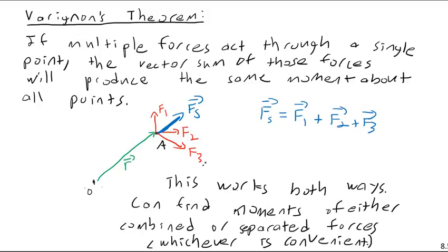Now, where this is really useful is especially for two-dimensional problems. When I say separate forces, that includes components. In many two-dimensional problems, it's very beneficial to simply take the moments of components, because with those, it's very easy to calculate perpendicular distances. We will see that coming up in a bit. So Varignon's theorem is a very useful tool for calculating complex systems of moments, which we will see when we come back from the break.